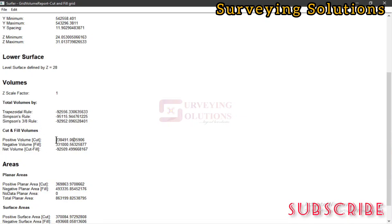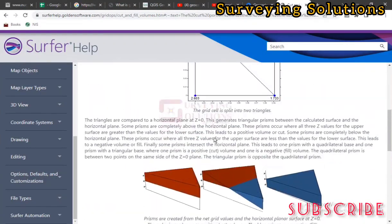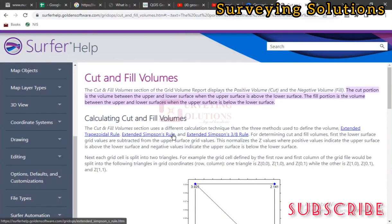So these are the different values we've told you. The positive values are the values you cut, the negative values are the values you fill, and then the net value is the value that is left. And since it is negative, it means it is to be filled, right? Good, it's to be filled. And we have a documentary, an explanation from the software on how this cut and fill volume works.